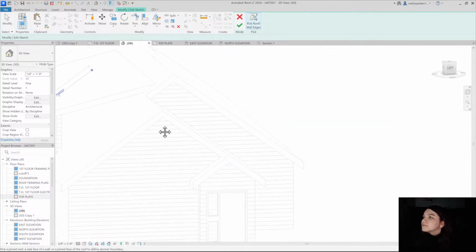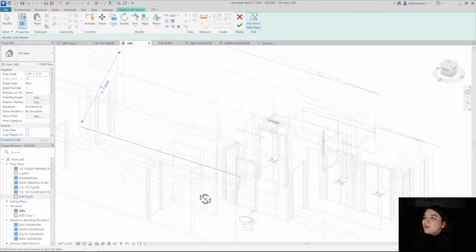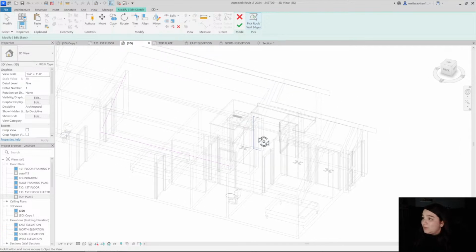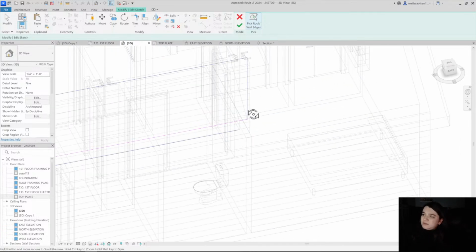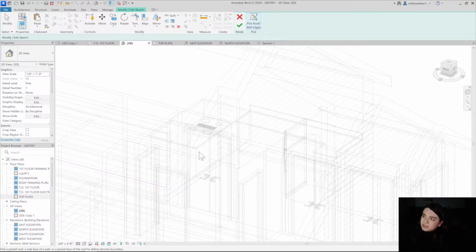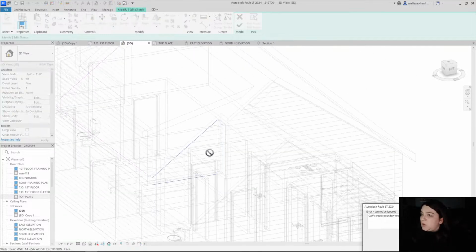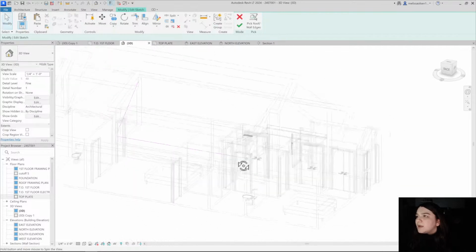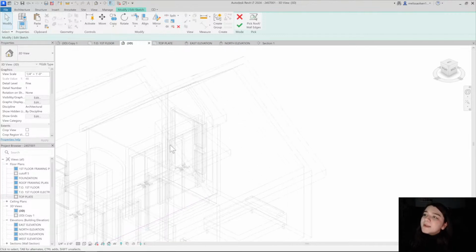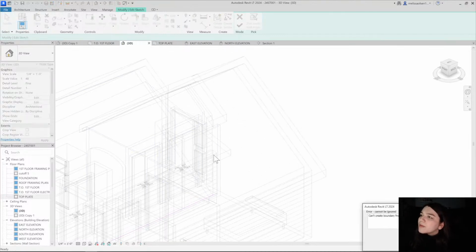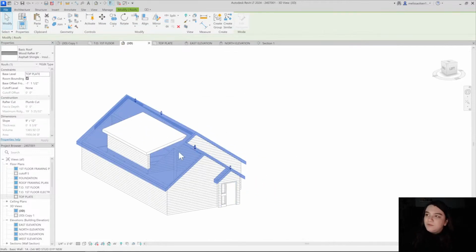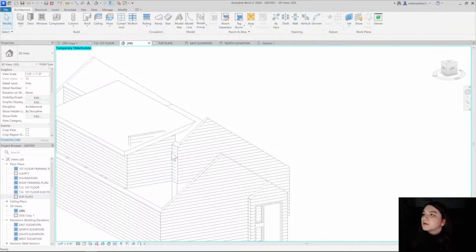Okay. And then, of course, my wall is all the way out in space. Can't create the boundary. Probably because I don't even know what I just selected. Why isn't it working? Pick. Can't create a boundary from your pick. Why not? Am I picking the right wall? Weird. Okay, let me exit. I think I need to unjoin this before.